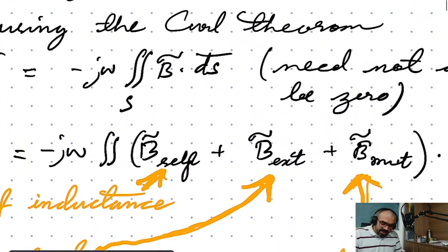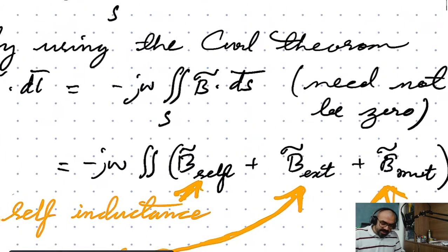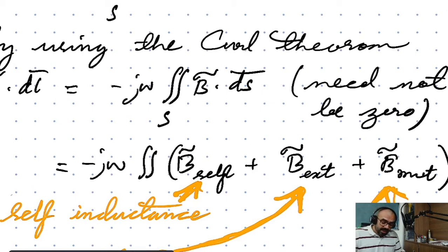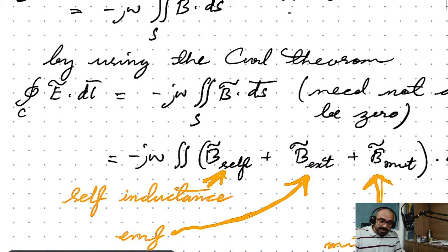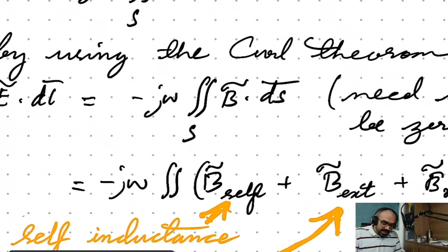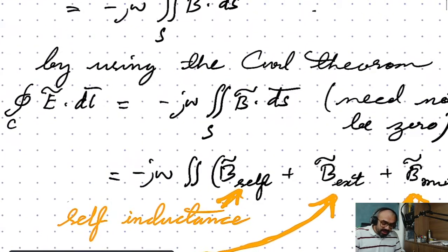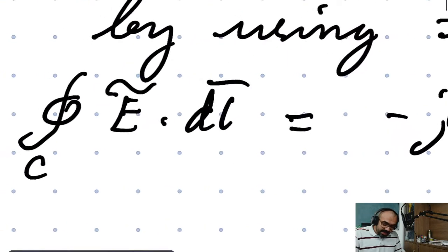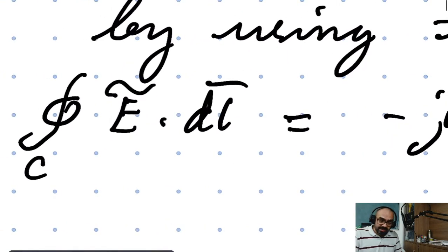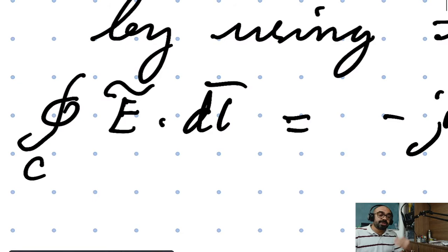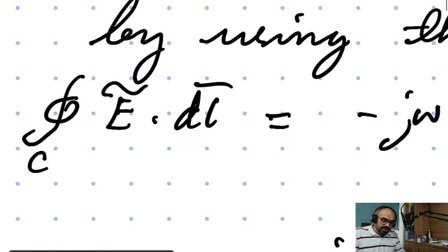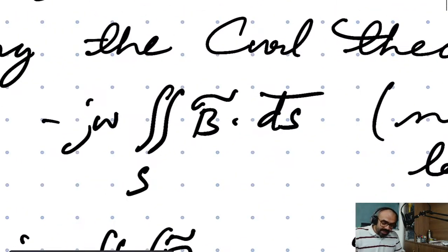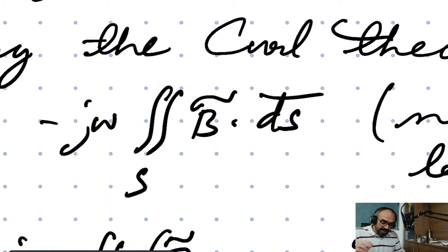In order to make it a little bit more clear, first of all, I want to see that this term is not zero in general, and you can only neglect it if this term is small compared to the sum of terms that make up the left hand side. Remember, the left hand side is the sum of potential drops across components. So this term has to be far smaller compared to each of those terms in order for your analysis to be more and more accurate.